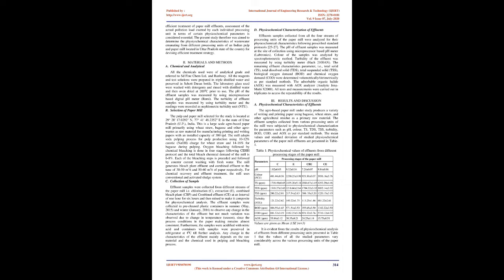Materials and methods. A. Chemical and analytical. All the chemicals used were of analytical grade and procured from SD Fine Chem Limited and Ranbaxy. All the reagents and test solutions were prepared in triple distilled water and preserved in short Duran bottles. The laboratory glassware used was washed with detergents and rinsed with distilled water and then oven dried at 200°C prior to use. The pH of the effluent samples was measured by using a microprocessor-based digital pH meter, REMI. The turbidity of effluent samples was measured by using a turbidity meter and the readings were recorded as nephelometric turbidity units, NTU.